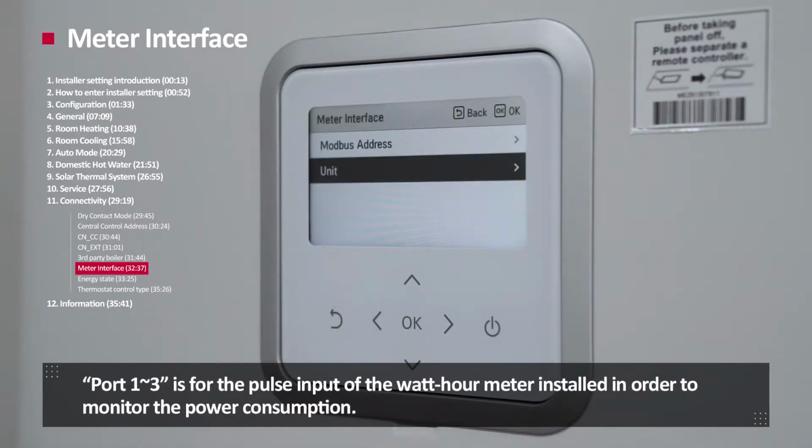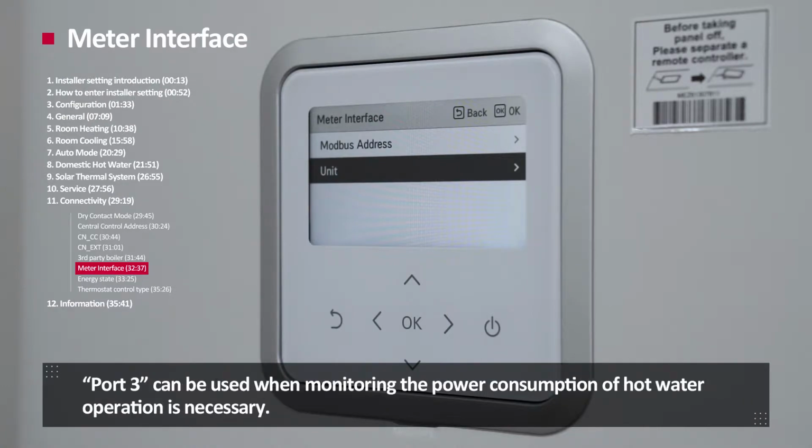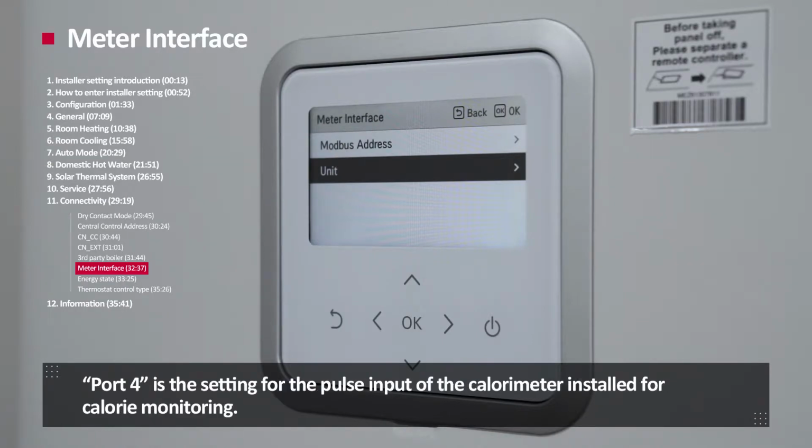Port 1 to 3 is for the pulse input of the watt-hour meter installed in order to monitor the power consumption. Port 3 can be used when monitoring the power consumption of hot water operation is necessary. Port 4 is the setting for the pulse input of the calorie meter installed for calorie monitoring.